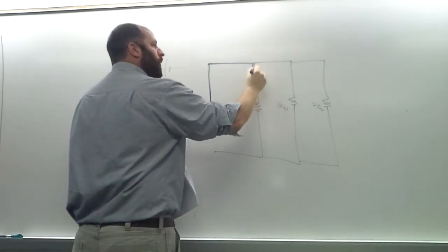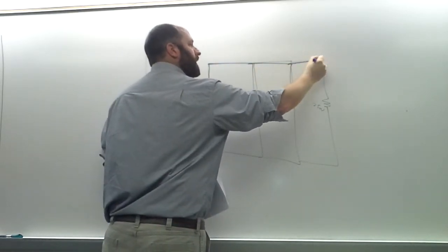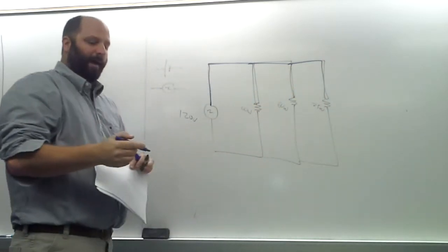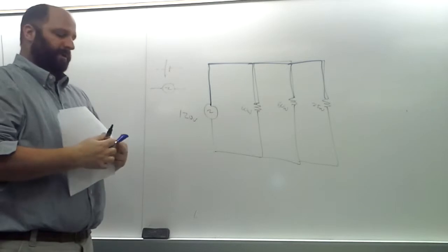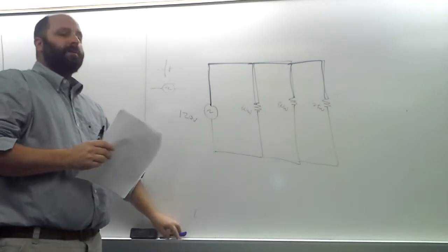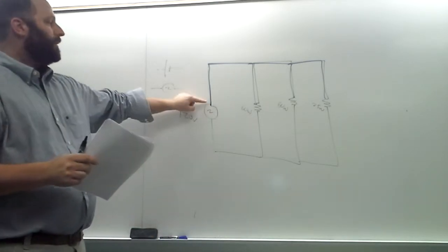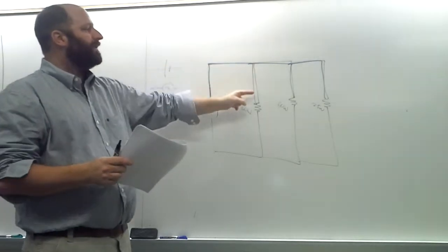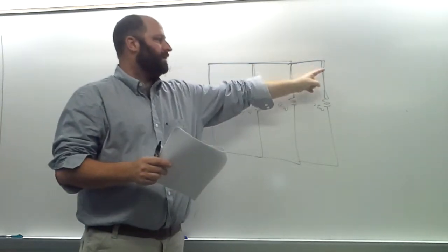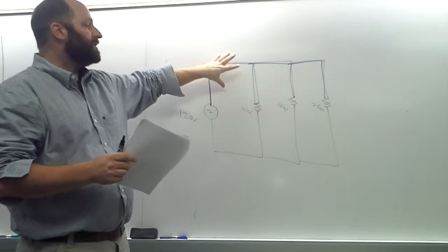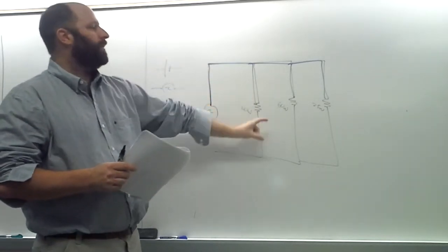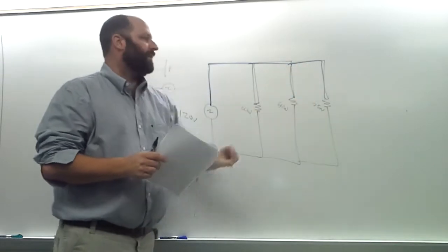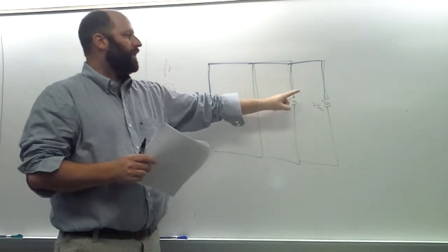This would all be one potential because this is all conducting material. Remember the I facts. One of the very important I facts was no electric fields in conductors, so the conductor itself is an equipotential. Now remember, in the picture, these are all wires made of aluminum or copper or some conductor. So this blue is all one potential. So blue to black, 120 volts. Blue to black, 120 volts, 120 volts, 120 volts. So it's 120 volts across every one of these.